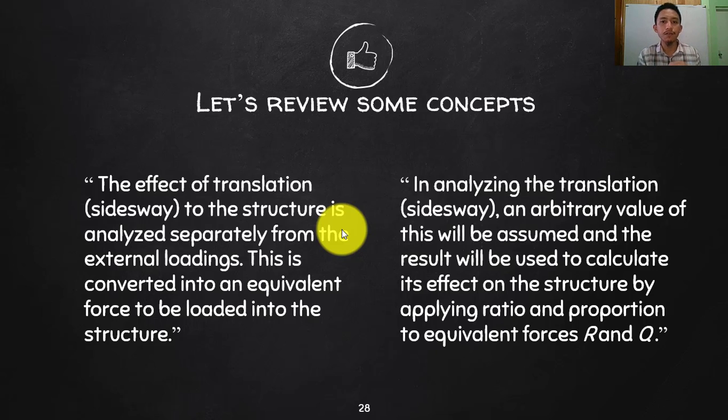Summate, and then of course just like what we did, if you have your end moments, get your end shear, transfer on the joints, solve for reaction. Once you have reaction, you can solve your shear and moment diagram, or you can draw your shear and moment diagram. Okay, so that's it.